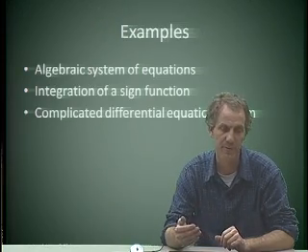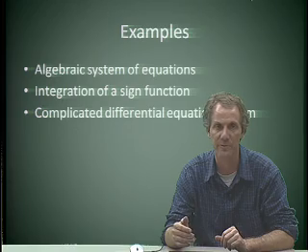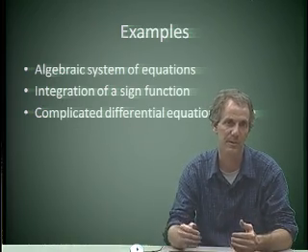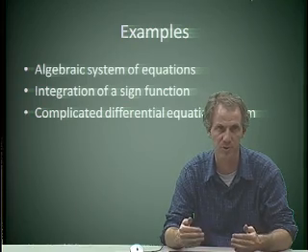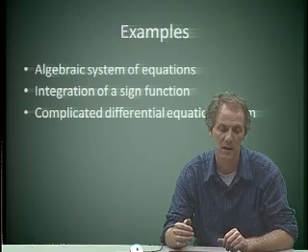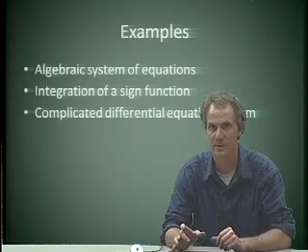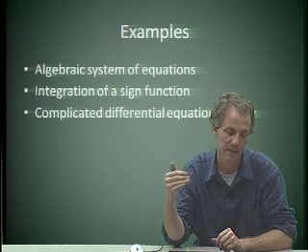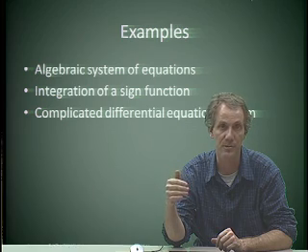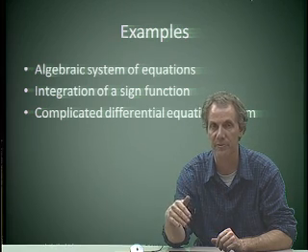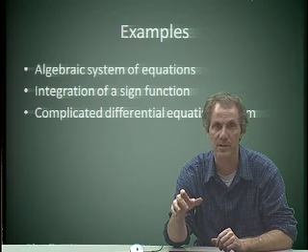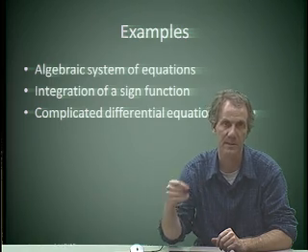The examples, I'll go through 3 separate Simulink examples that are on the website, starting from just pure algebra, which really isn't the strength of Simulink, but it shows you how the block diagrams work. And that's the assignment I've given you. I've given you an algebraic assignment, so definitely pay attention to that. Then I'll also show integration, just straightforward integration of a sine function. And finally, I'll show you how you could solve a complicated differential equation. It's a detailed example.